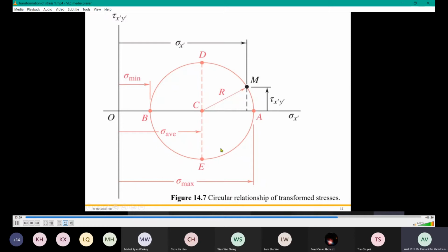But you are going to draw a circle for the given points x and y, the points of shear stress and normal stress. The coordinates are normal stress and shear stress. These values are changing, hence you need to find out the value. The coordinates of these two will be given to start with. Once you plot these on this plane, you will make a circle to find the minimum and maximum. From 0, the normal stress value is very far, very high. At the same time, the minimum and maximum all happen when shear stress is 0. See, this is where shear stress is 0.